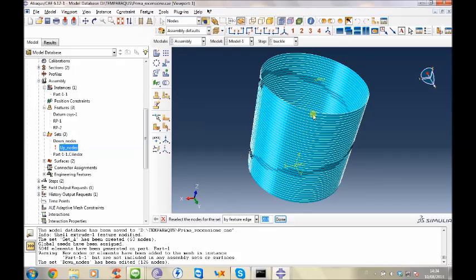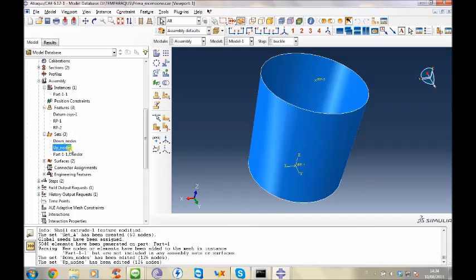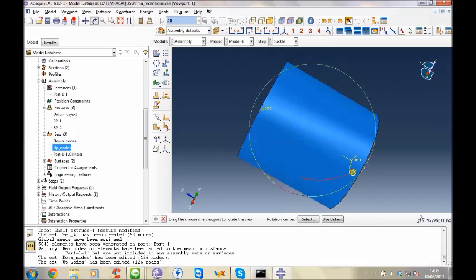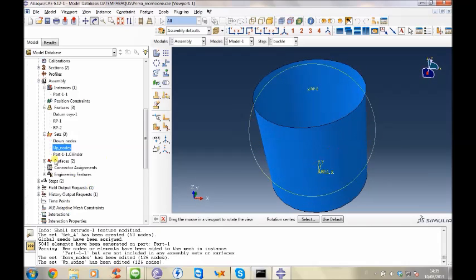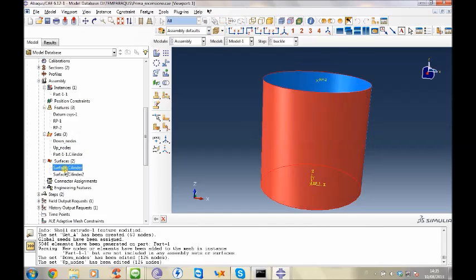Okay, done. It's pretty easy, but you have to do this always when you change the mesh. If you forget to do this, probably the analysis will be aborted. Instead, surfaces are selected using the geometry, and as you can see, they remain defined.